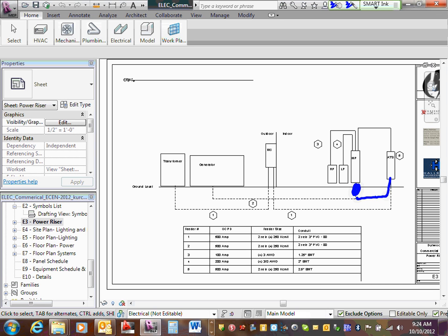So you're bringing the power guys from the transformer into the meter cabinet, out into the auto transfer switch. Then you bring a generator power to the auto transfer switch. Then the power goes from here into the main panel, and out of the main panel into these 2 sub panels. And that's what your project is, right?